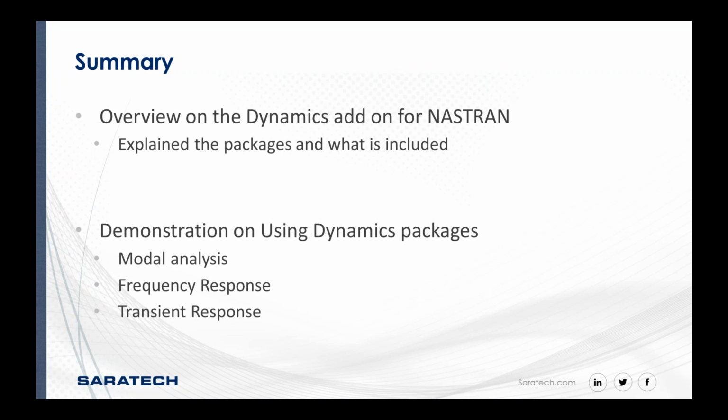And then hopefully my demonstration showed you that setting up these analyses inside FEMAP isn't overly difficult. Setting up the modal analysis, setting up frequency response, and setting up a transient response. The one thing to remember here is frequency response, we're in the frequency domain, transient response, we're in the time domain.